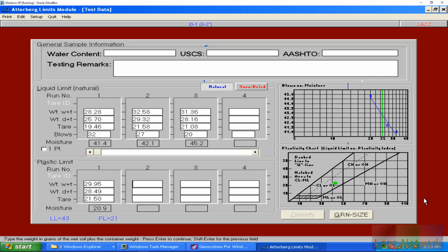Because you might think, and this is how detailed this can get when it comes to soil classification, you can have an elastic silt, but depending on where it falls on this table, if an Atterberg limit is performed, it also depends on the wash and the grain size. That is going to help determine if it is an elastic silt or a lean clay or a fatty clay, because it could fall anywhere in that group. But it's with the actual laboratory testing side where you can definitively classify it. So that's one way of doing it. The second way is through, as I kind of covered a little bit, the actual testing aspect.